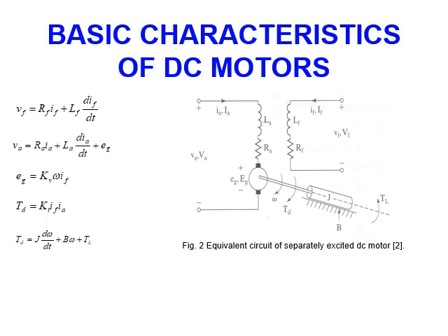Now for the DC motor, let me start with the separately excited DC motor. As you can see here, we have the armature circuit and the field circuit. We have inductance and resistance on the field, and inductance, resistance, and back EMF on the armature, and a shaft connected between the armature and the load. Also, we have angular speed and delivered torque, while here we have the load torque, moment of inertia, and viscosity.